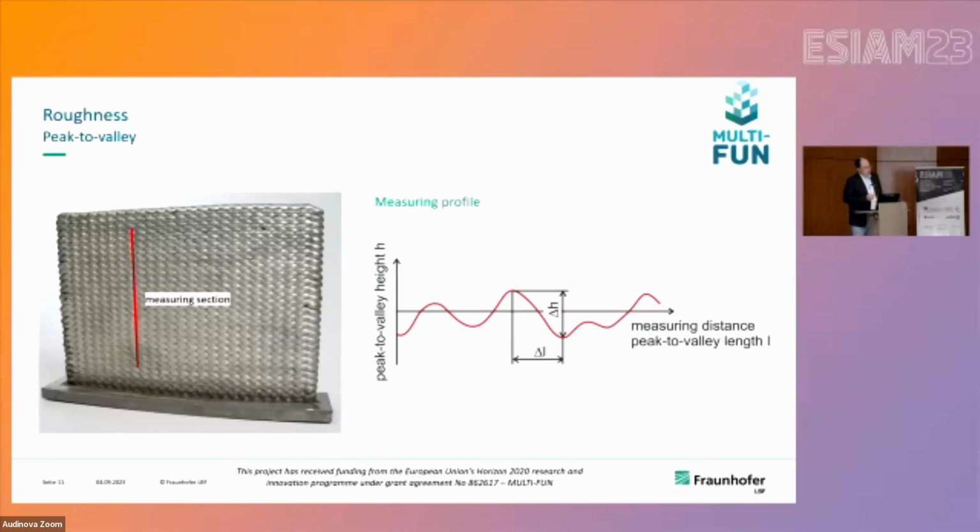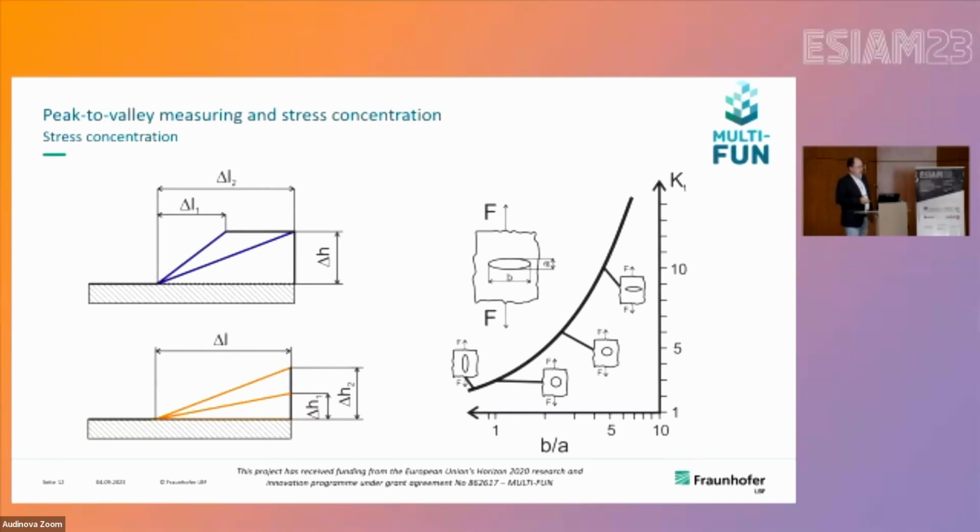And with our experience in analyzing such profiles in fatigue, you can imagine that the different parts could be notches. This means this profile is a sequence of notches. On the other hand, you can also analyze, with common tools of fatigue, the frequency of these different notches. And therefore, let's start with the notch effect.